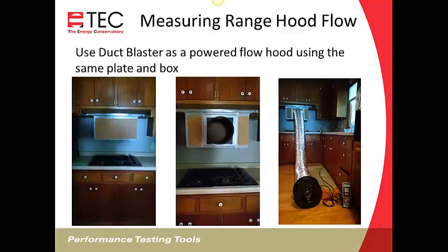Okay, the second method we talked about was using the Duct Blaster Fan as a powered flow hood. So in this case, I used that same box. It's the right size to make it work, and I just used some duct mask to cover over the lower hole on it.